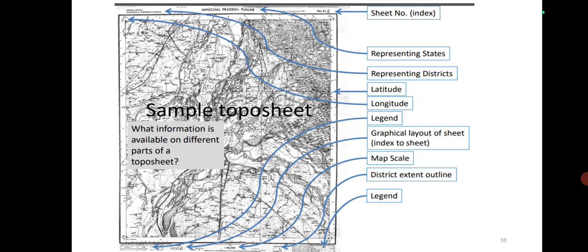Then the height also will be calculated using trigonometry. Then benchmark will be shown. Then if it is mixed forest, with more than 2 varieties of trees growing in close proximity, it will be marked as mixed forest. Then open jungle, then embankments or raised soil or raised areas. Form lines: the form lines are contour lines, but they show only approximate height above sea level, and they are just used to indicate the elevation of the area, which is not accessible for proper survey.